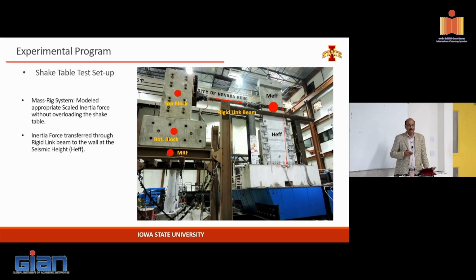So ideally, if you're doing a shake table test, all you have to do is, this is the shake table here, this is the foundation, here is the post, this pocket was put in so that we can access the post tensioning, so we can hold the anchorage and then actually apply the post tensioning. This is the effective seismic height calculator, so that's where your seismic inertia should be generated. You could leave a mass here,